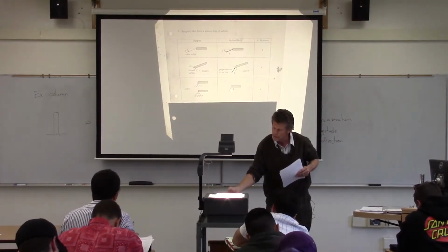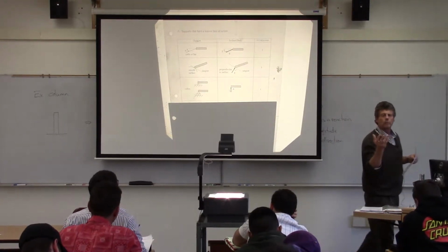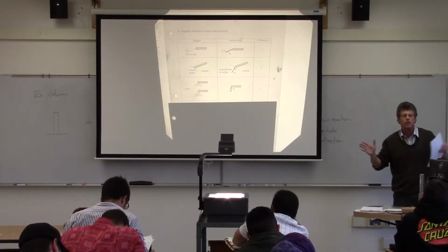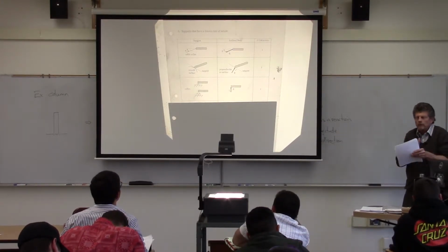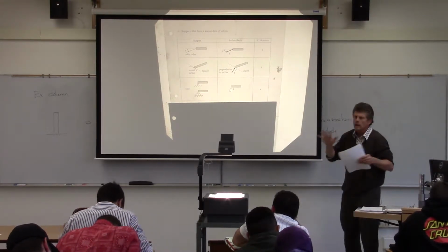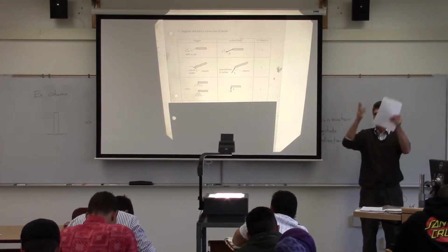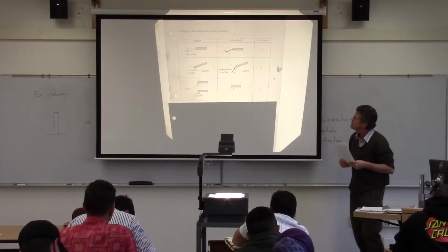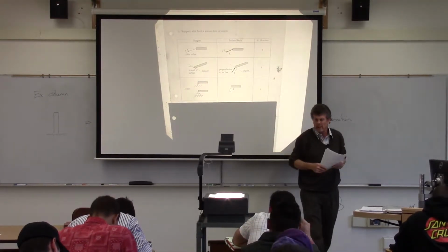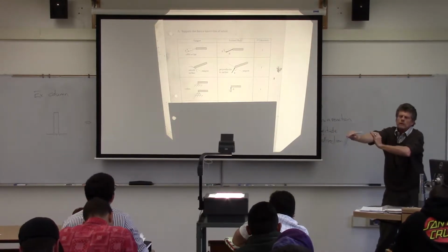Okay, another one that we run across is what we call rollers. Now, we see these a lot on bridges and stuff. When you go over bridges, you hear the bam, bam, bam. Those are expansion joints. Basically, bridges have to expand in the heat and contract in the cold. And if we don't create these joints, what we're going to find is roadways buckling and that sort of thing. So these rollers we represent in terms of static with a wheel or a little triangle with wheels and stuff like that. But they're the sort of things we see on bridges.